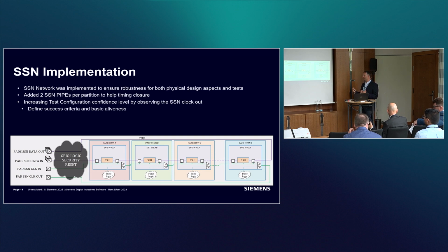I can shift in data at a 400 megahertz rate, and eventually I will use a 50 megahertz or 100 megahertz shift. This way I can see that the test engineer is using the correct pattern, without opening a simulation and looking at the waves. I'm going to use that to see the shift clock live.